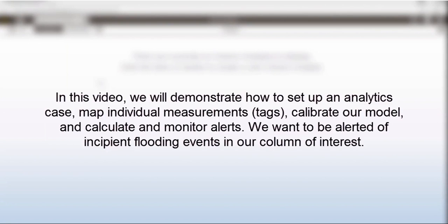In this video, we will demonstrate how to set up an analytic case, map individual measurements or tags, calibrate our models, and calculate and monitor alerts, so we can be alerted of incipient flooding events in our column of interest.